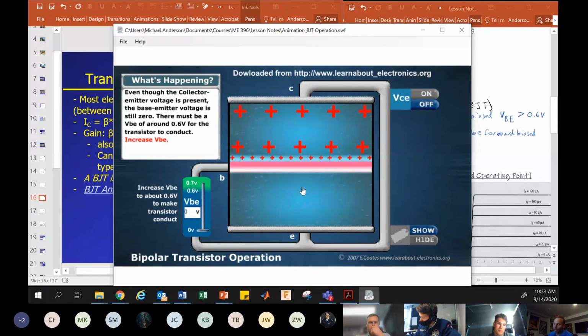Physically, what happens is when we get the transistor forward biased, meaning we built it into a circuit that is appropriate for that transistor, there will be an attraction for the electrons to be pulled from the emitter into the base. The base is so small that most of the electrons can't make it through the base. But the attraction is so strong that it pulls those electrons towards the base with a lot of momentum, and the momentum actually pushes them across the depletion region into the collector.